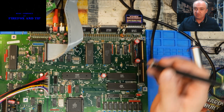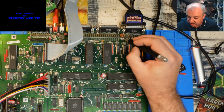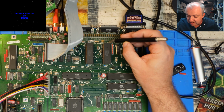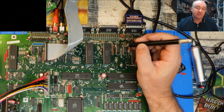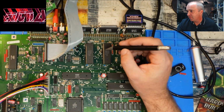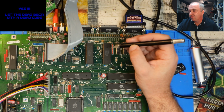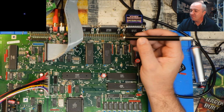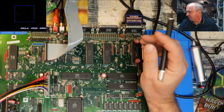Although we can see a large trace running down here. Do need to be careful here because the machine is switched on, but the trace from the left side of C215 runs down along here. It's quite a big trace. So we could cut the left hand side of it there, bend that round, scratch a bit of that solder mask off and make it off onto the trace just there. That is supposed to give us a better video signal, although to be honest, the video signal that it produces, well, to me anyway, it looks just as good as any other Amiga. But it's a recommended modification, so let's just do it.